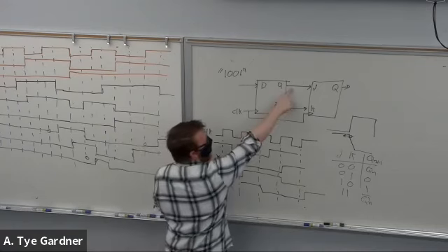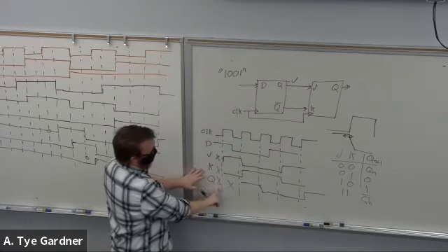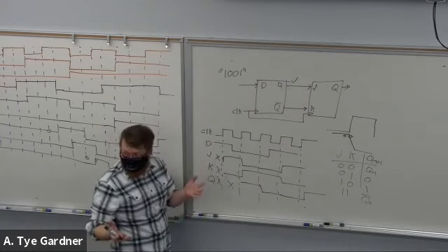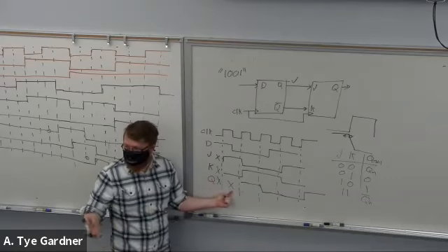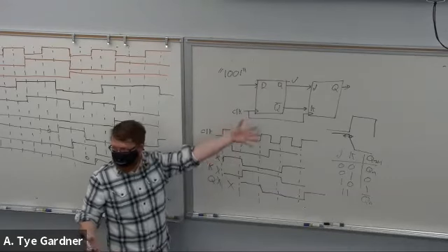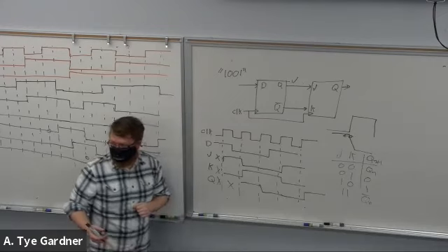The output, J, can update. But at that same clock edge, it's clocking in J and K, which are don't know. So the output after this clock is still don't know, because what is the J and K? And then finally that is propagated through. Thank you. Yeah.